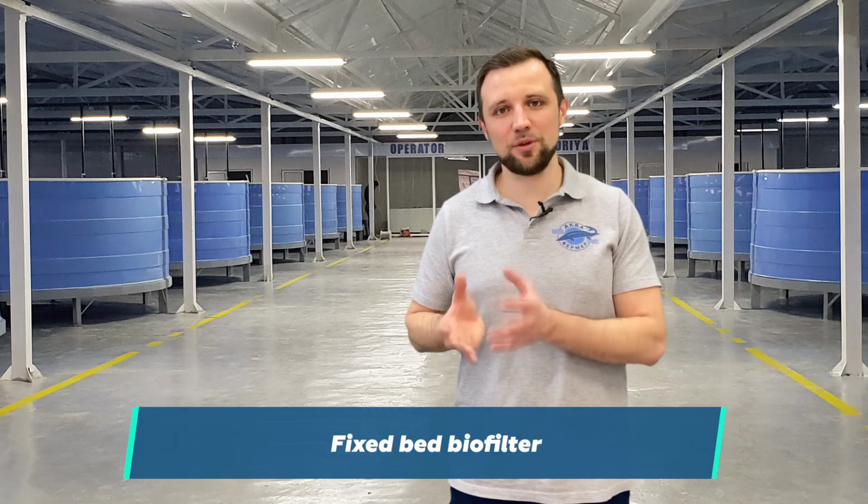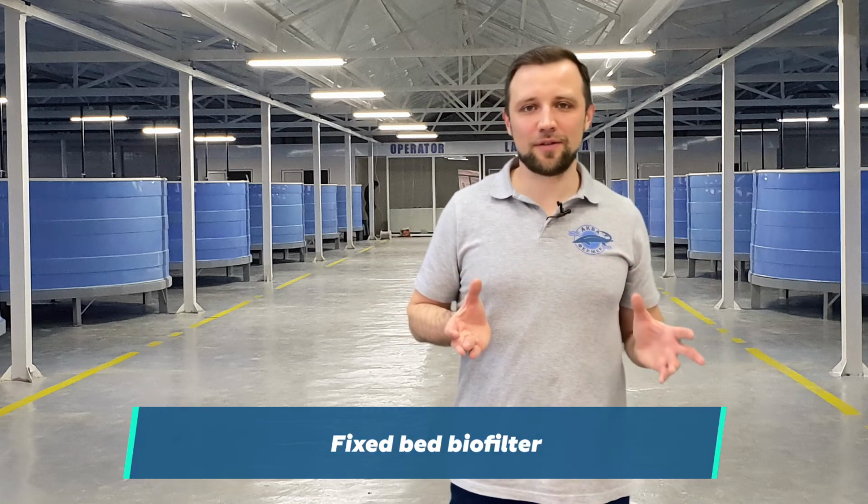Why do I also recommend this biofilter? In addition to biological filtration, it's very good at retaining fine suspended solids, which are not retained by the drum filter mesh. All suspended matter, following with the water current top-down through static media, is retained on the media, so you actually have another step of mechanical treatment, and on the whole the water in the systems becomes better treated.